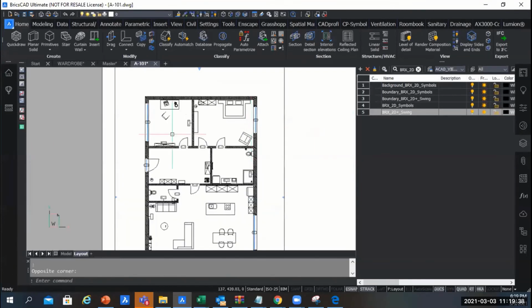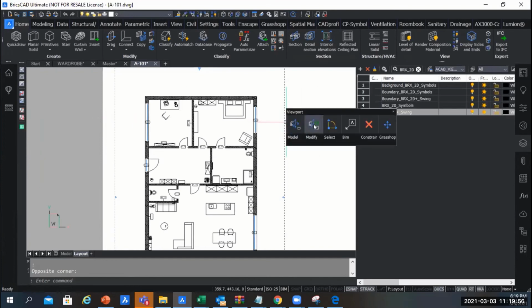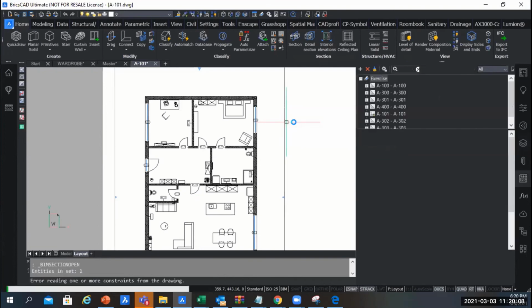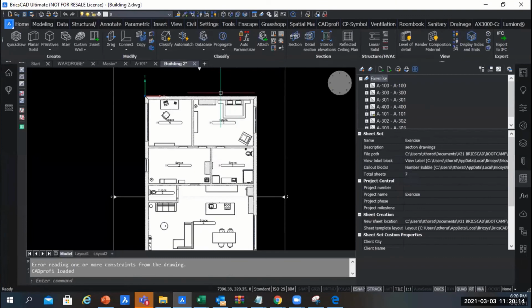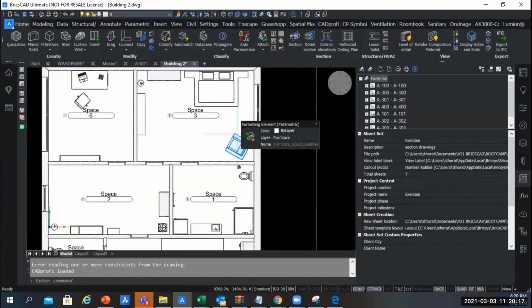Now let's make some changes to the BIM model and update the floor plan. Open up the section in the 3D model, and then we will do that. So how can we do that? We can simply go to this view, and you see there is this open model symbol. Use this symbol and directly open the model in the 2D view and 3D editable view, which is now getting opened here. Okay, there you go. This is 3D, but you can work in 2D.